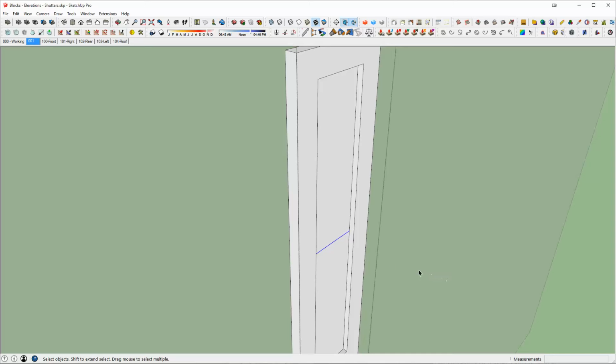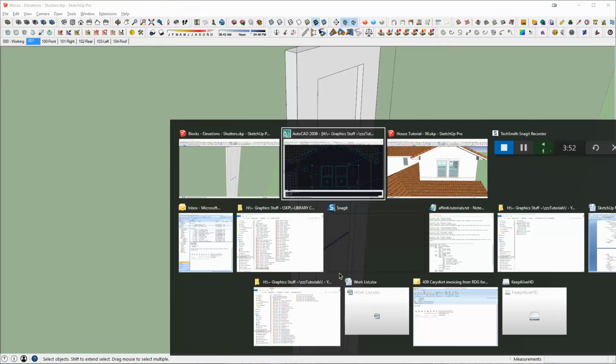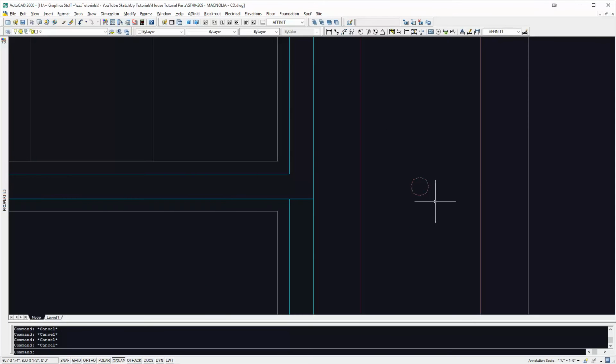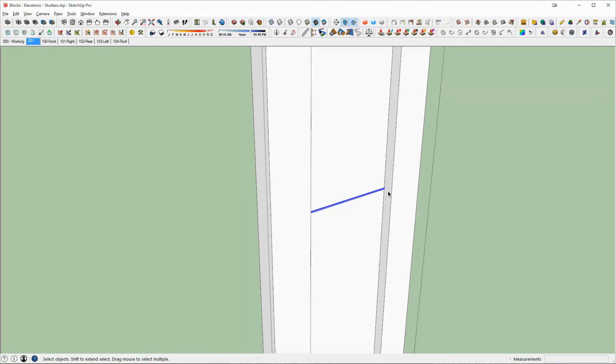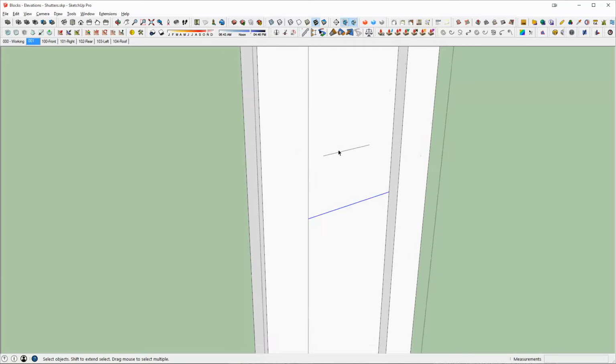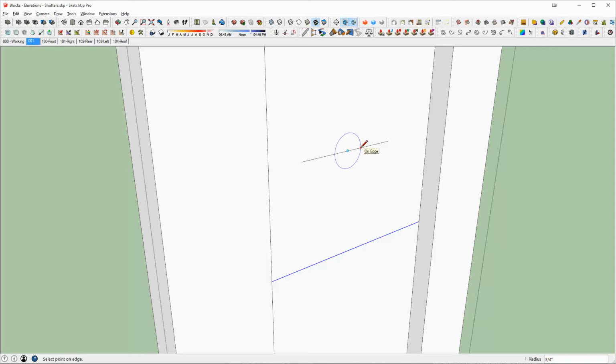drilled hole here in the center. We will look at this detail once again, check the radius. It's 3/4 inch, so 1.5 inch diameter. I drew this line, this gives me my center point, but I also turned it into a group, and I'll show you why. If I were to have left it as a line and then tried to draw my circle at 3/4 inch, this line is going to split my circle, which I don't want.